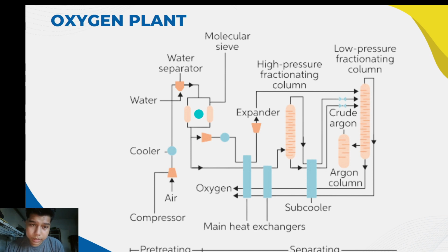The pre-treated airstream is split into two. First, a small portion of the air is diverted through a compressor, where its pressure is boosted. So here is the compressor. It is then cooled and allowed to expand to nearly atmospheric pressure. And this, the blue circle, is the cooler. This expansion rapidly cools the air, which is injected into the cryogenic section to provide the required cold temperatures for operation.